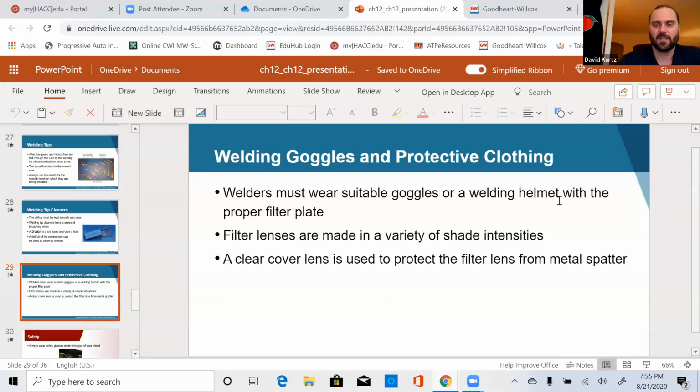If you're going to use your welding helmet, you want it to have a grind mode so that you don't go dark, especially if it's an auto darkening one. If it goes dark on you, it's going to make it a lot more difficult to weld or cut. Most auto darkening helmets nowadays have a grind mode so that when you have a spark or a light or whatever, your auto darkening doesn't go dark. It stays see-through so that you can see. Usually your basic filter lens is, I think, a 7. So you'll be more than protected if you're going to wear your welding helmet. You just want to make sure it's on grind mode.